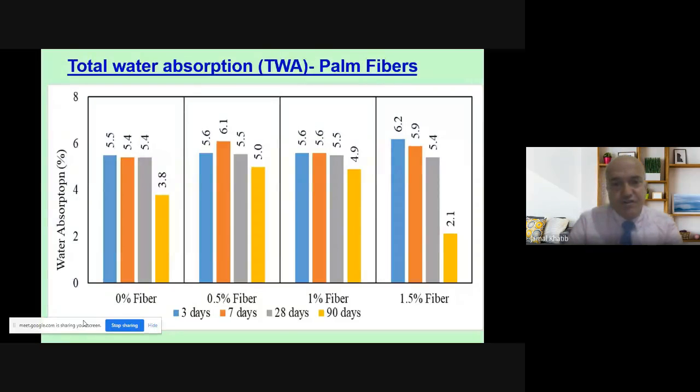And of course, with lower water absorption, technically, we should get more strength. And we try to explain the results. Maybe we have isolated pores, and these will not appear when we do the total water absorption. So that is one thing we might look at closely in the future, and do SEM studies on various specimens and see how they vary.